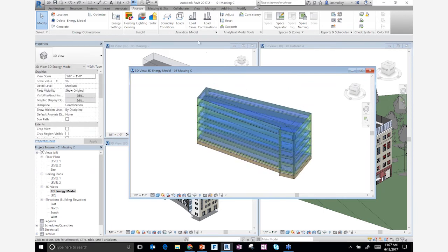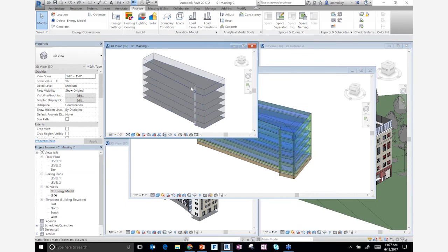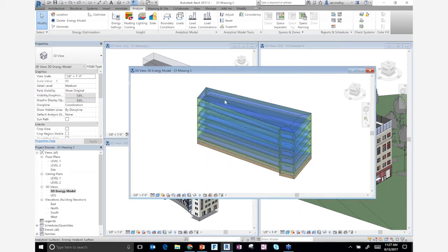And you'll notice there's no glazing in this model, because glazing is both a set of decisions you need to make as well as time-consuming to actually add to a model. And it's good to do the analysis even before you start to add any glazing to the building, because we'll analyze that in Insight 360 to see what opportunities there are and the impacts of putting glazing in different parts of the building. But basically what you'll see here is we've applied 40% by default.